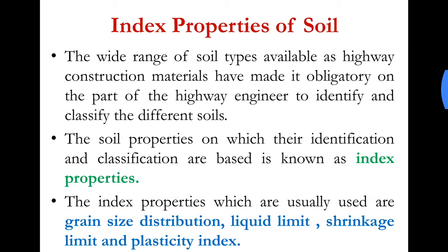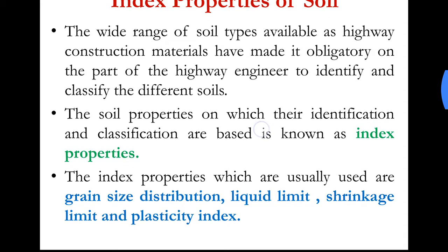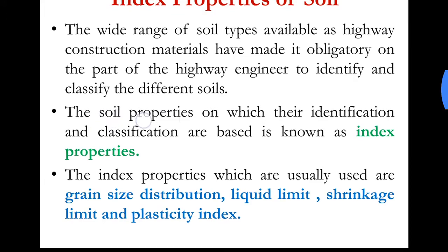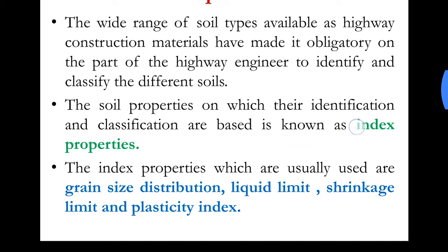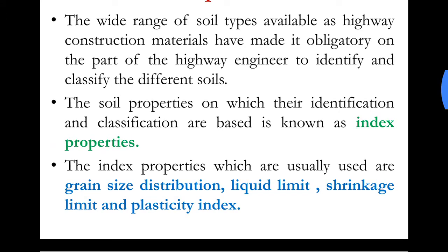Since a lot of different types of soils are available, we need some properties or features in order to differentiate or classify them. Index properties are one of those properties which help us to classify the soils. The soil properties on which their identification and classification are based are known as index properties.